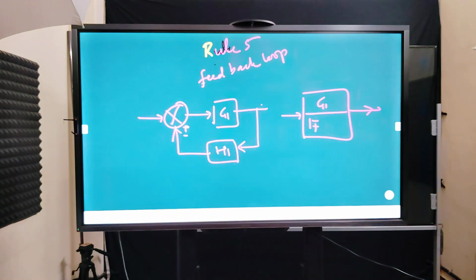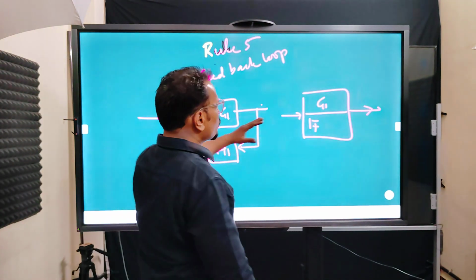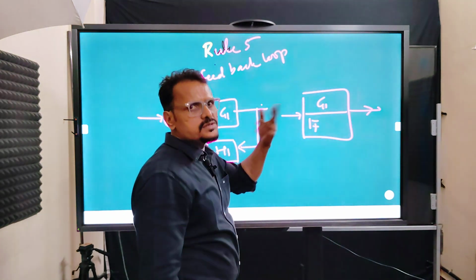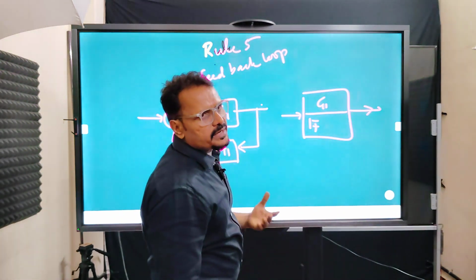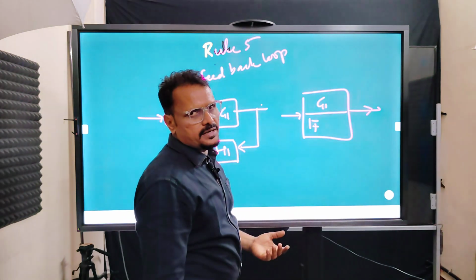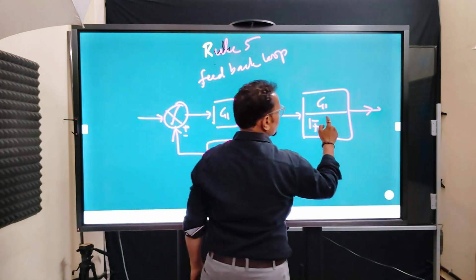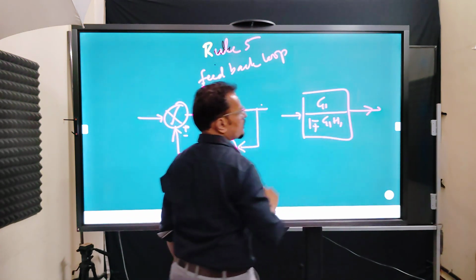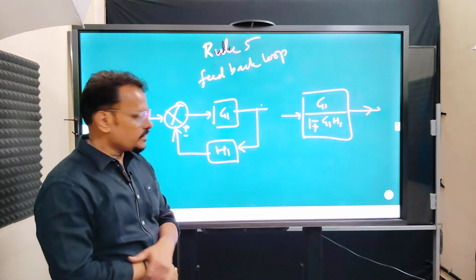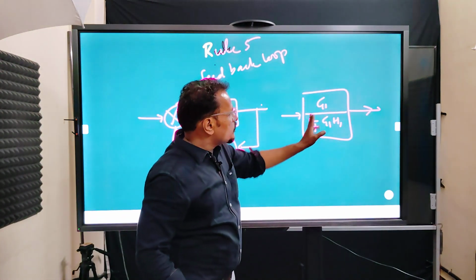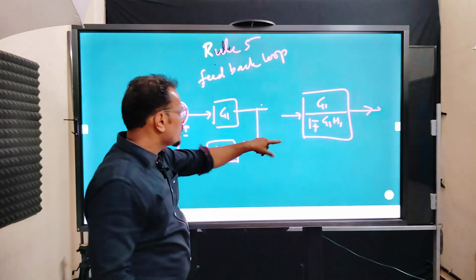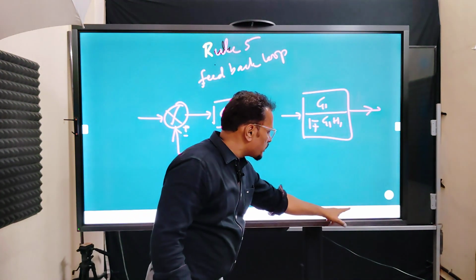Okay, so that we have to do. Let me check it out once. Correct. Because a negative feedback will make the system more stable. A positive feedback will make the system kind of unstable. So we'll get it as forward divided by 1 plus forward multiplied by feedback gain. This is the way we can write it also. Here, write the gain on top as it is, and below write 1 with the sign reversed: if it is plus then minus, and if minus then plus. Now we'll go to our example.